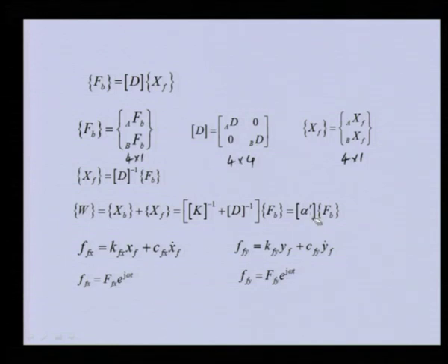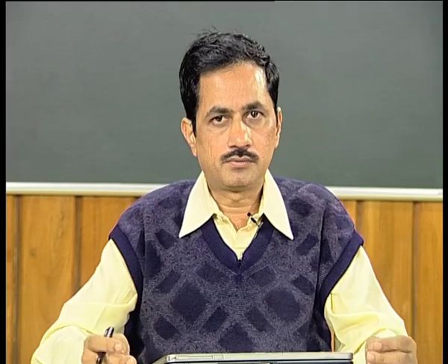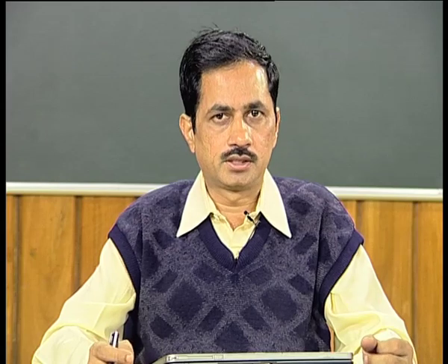This particular expression is representing now both the flexibility of the foundation or the pedestal as well as the bearing. So, this equation can be clubbed with the previous equations to get the final unbalanced response of the disc. In this analysis, when we are considering the pedestal or foundation flexibility as well as the bearing flexibility, we obtain the effective flexibility they are imparting, and then we can add that with the shaft flexibility as we did in the previous analysis.